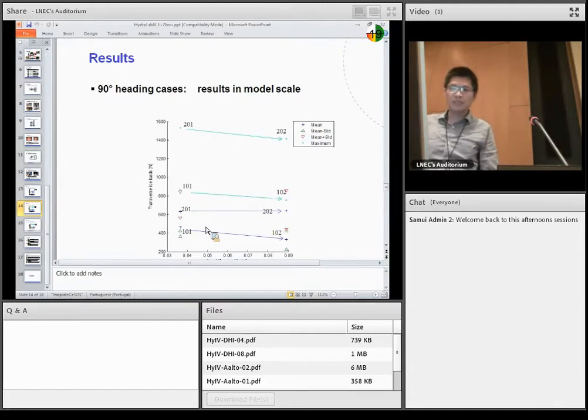This data is not directly used for engineering, because this case is, for example, 90 degrees. You can't design a ship with 90 degrees and fixed at that angle. Actually, we try to do it in the marine system, with the marine system, and release rotation. And of course, when the ice comes in sideways, the ship could move due to its ice moment and turn towards the coming ice.